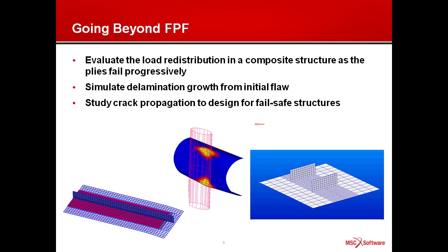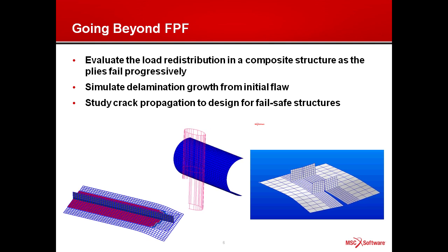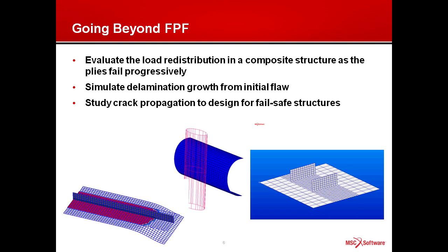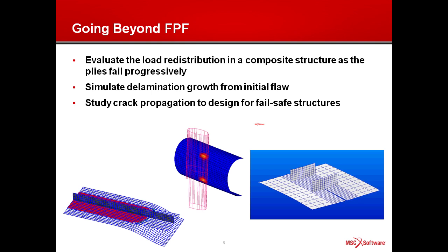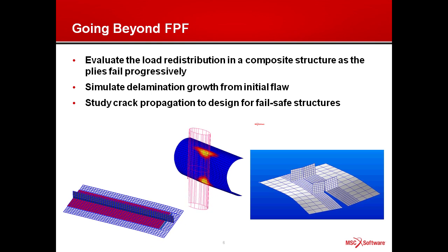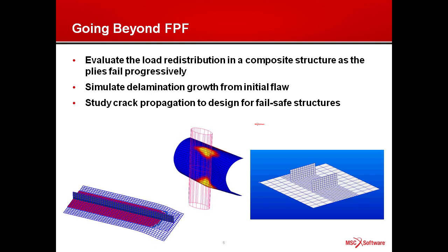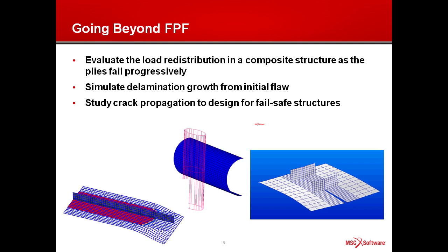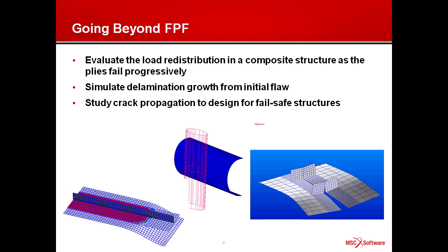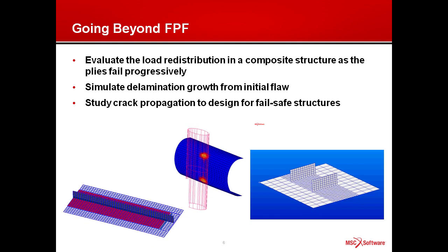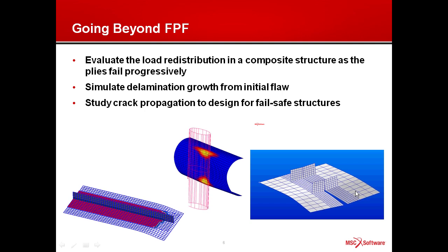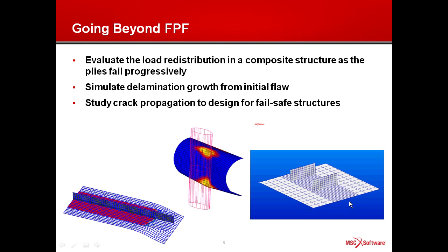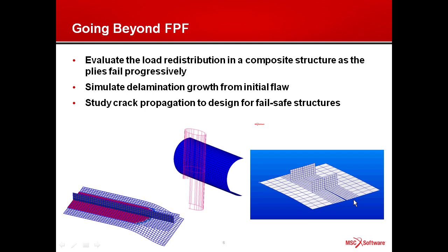You may also want to study crack propagation in the structure, and maybe you want to find out, is the structure fail safe? Can my structure contain the crack growth within a stringer bay or a frame bay? Here's an image of a crack propagation through a stiffened panel. Again, an example we'll also take a look at later.